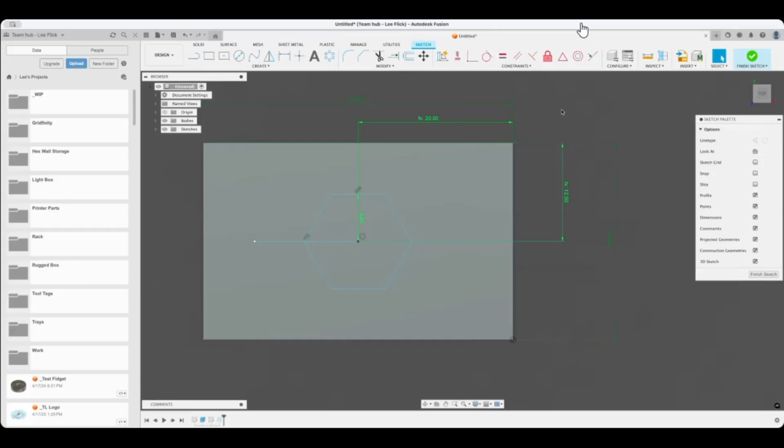So what Eternity said is, I'll show you what I just did. All right, Control Z. All right, so it's kittywampus, right? So let me get rid of this line. So here's what we're gonna do. On the menu bar, across the very top, the very left one is line. Okay, click that, and then go to the center of the hex.